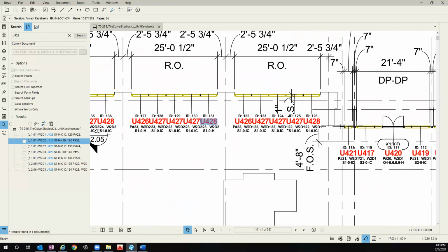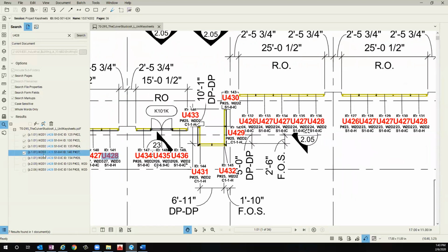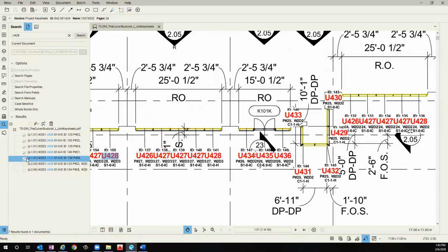So here, one of the steps that we'll be doing is after we find the unit, we'll select it in each of the floor plans, verify that dimensionally that's correct. We'll correspond that with the elevations as well. We'll check this on our shop drawings to make sure that there hasn't been something that's changed. Once we verified that this is correct for that spot, we're going to select these check boxes. So after we've done those specific steps, in this case, we're going to check all of these off the floor plans. And then here, that's floor plan.